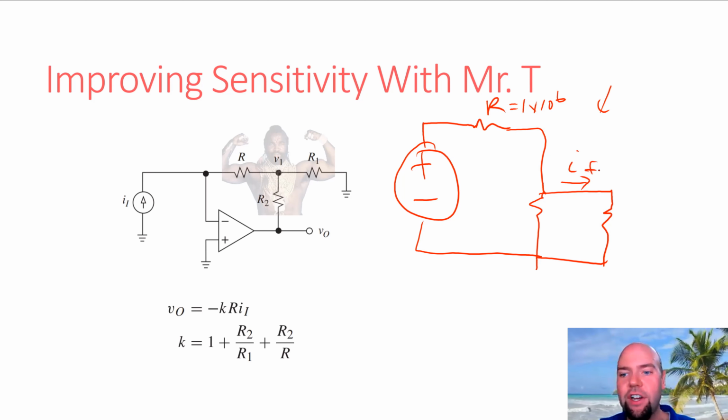Not a voltage divider, sorry, a current divider. So basically we now want to split this, and let's make this one 1,000 ohms, and let's make this one like 1 ohm. So now we have our voltage converted to a current, but it's not 1 billionth, it's 1 millionth. It's a humble millionth.